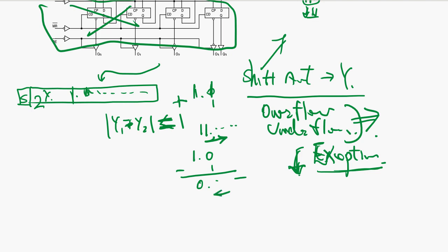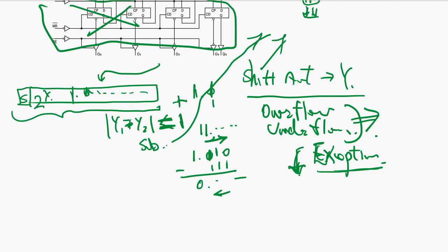That means we have to shift a bit here, and actually this may cause more shift. So if it's subtraction, we have to go through the same process of leading bit detection, and that's a lot of gates the signal goes through in order to have the final format. So that's addition.